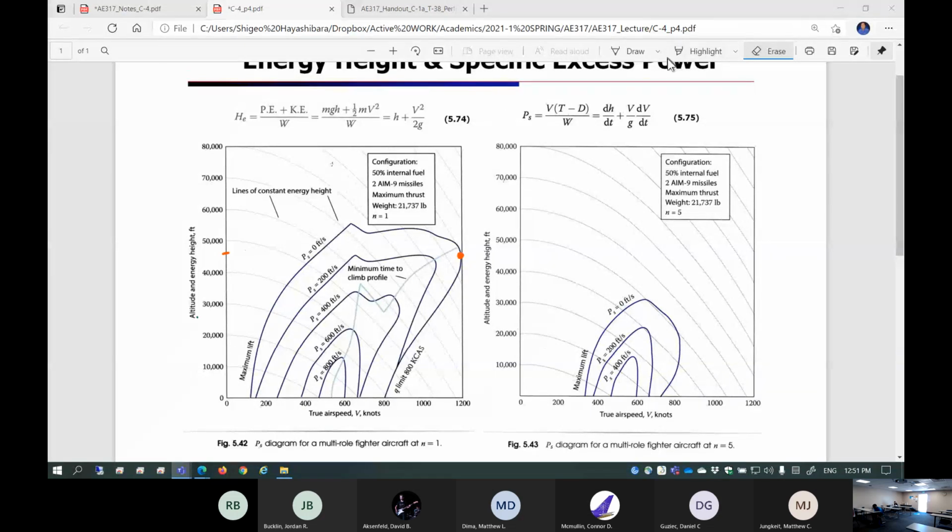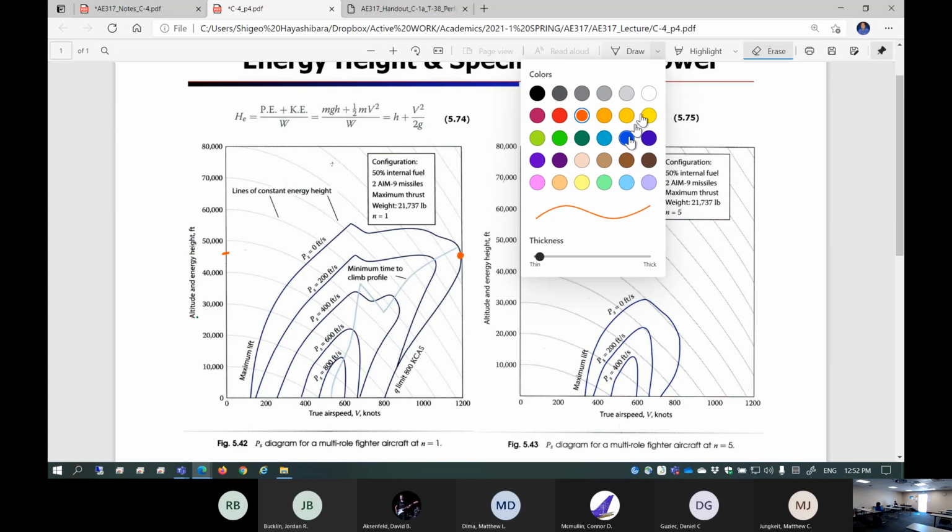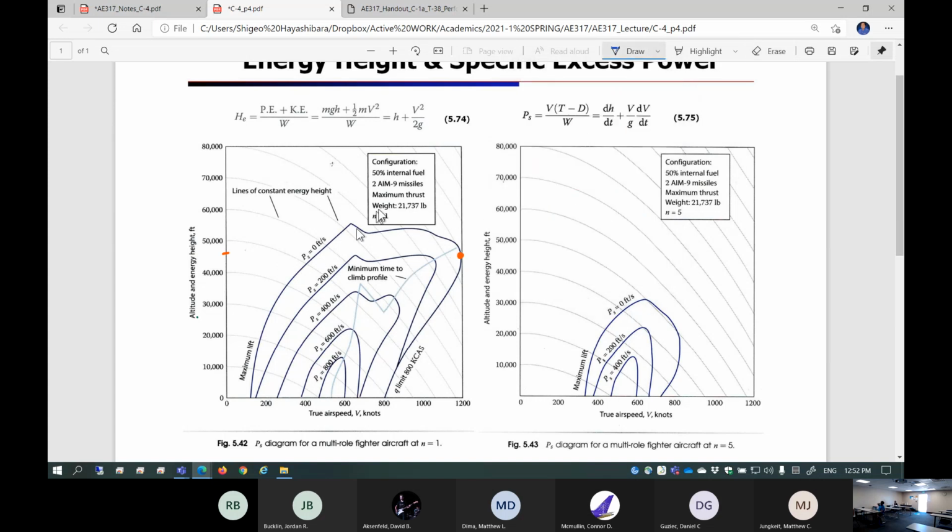So, is that maximum altitude where it starts the zoom climb, or where? Well, zoom climb is okay. Let's say zoom climb is you are somewhere on this PS equal to 0 contour. Suppose you start zoom climb from here, you are going to get this much altitude by giving up all the velocity. Is this absolute max?